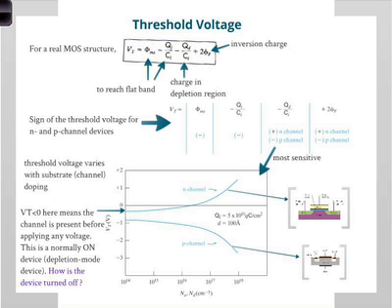Now the sign. The sign of the threshold voltage is important. It's important because the p-type substrate and n-type substrate gives you 2 opposite signs, like I said before. It's easy to get confused, so you have to understand one really well and apply that same physics to the other, same logic. Okay? Now, we'll look at that very, very briefly. But the idea for a p channel versus n channel is extremely important because in digital processing, the most common, most important, I would say, in terms of usage,